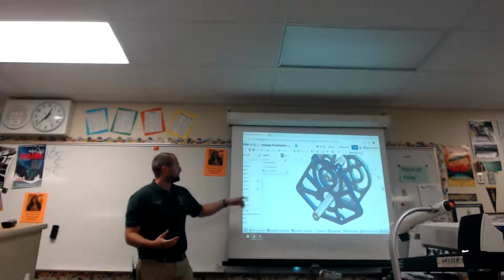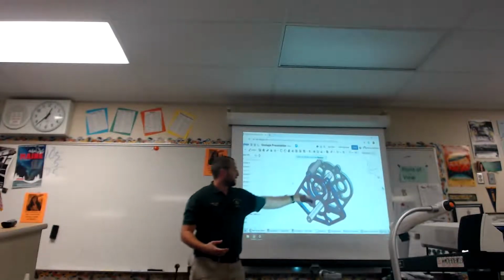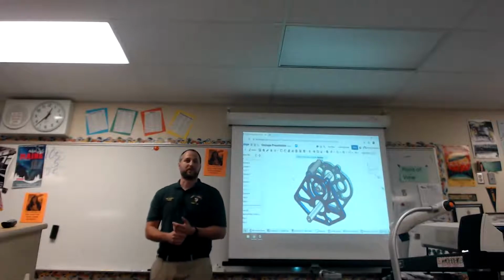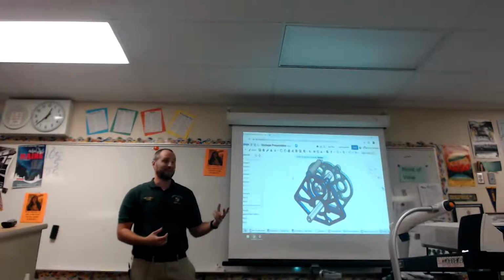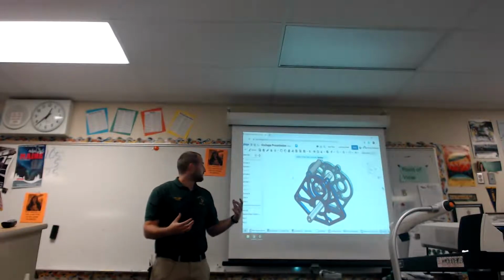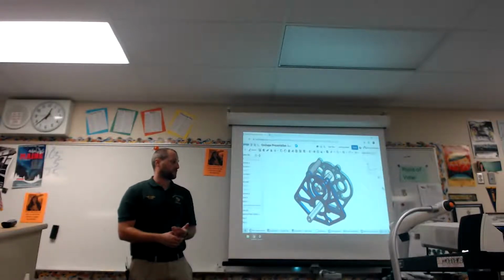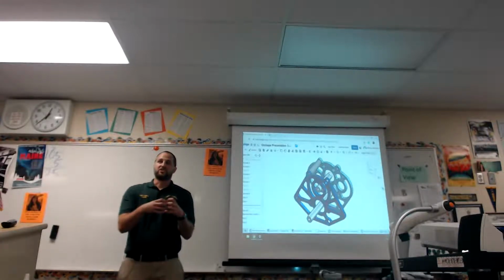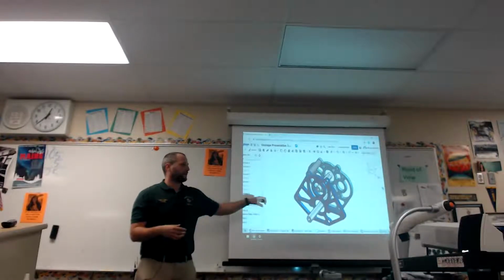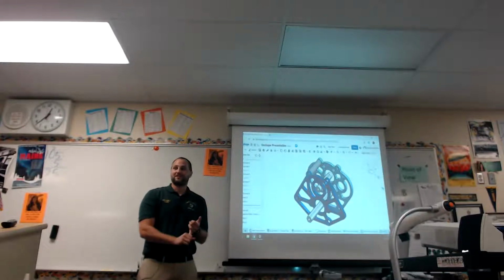What is unique is, go ahead and close out of that sketch and zoom out, Tony. 1, 2, 3, 4, 5 parts in this part studio that are all interlinked and joined together. Tony actually built this with the idea of making some modifications in mind. He has some variables he programmed in, but if you just change these manually, it would do the same thing. So we're going to switch out some different things, and you can see how this gearbox changes and everything adjusts all on its own together. Doing this way instead of in an assembly gives you some performance benefits because you're only calculating geometry. You're not calculating geometry and assembly constraints.